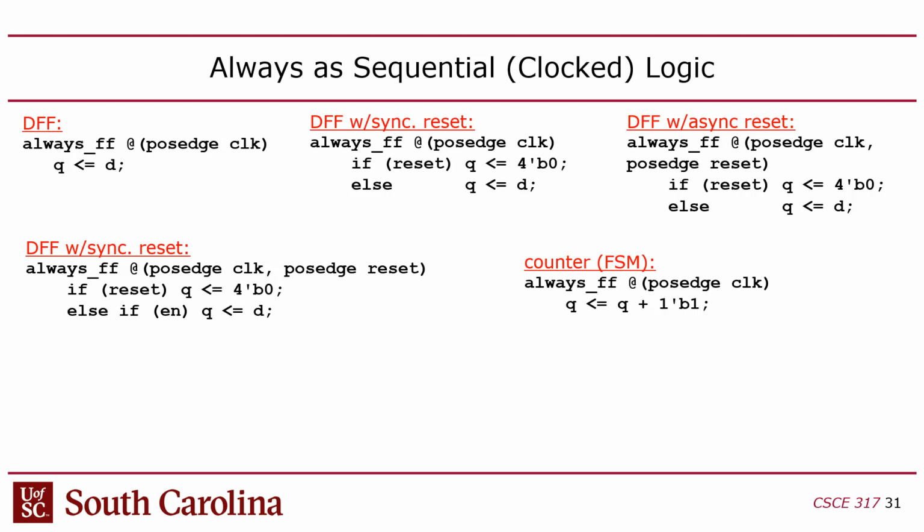It's just a type of memory that you can build in a circuit using cross-coupled wires, essentially. You have gates where the one output feeds into the input of another one, and then that one feeds into the input of the first one. So you have this cross-coupling of wires. This creates memory.